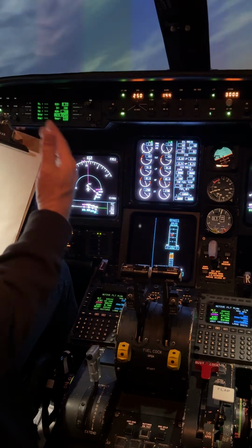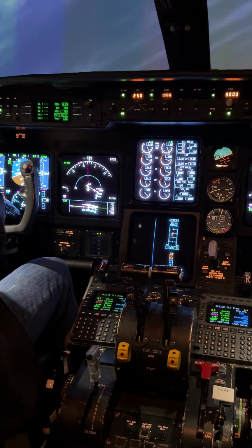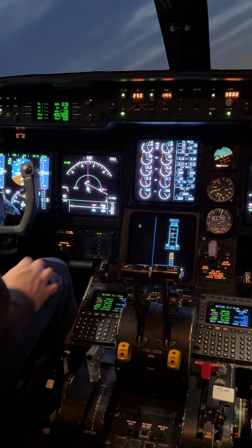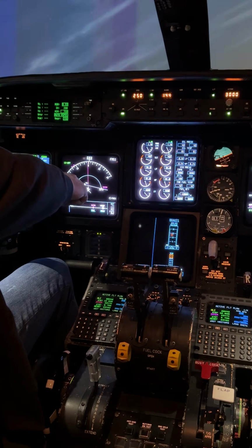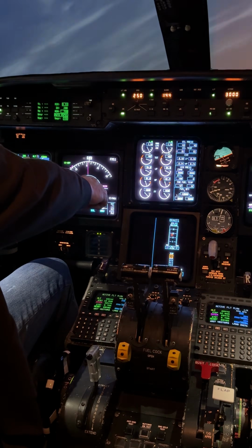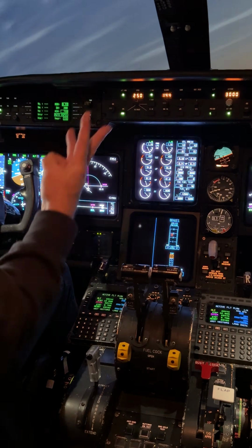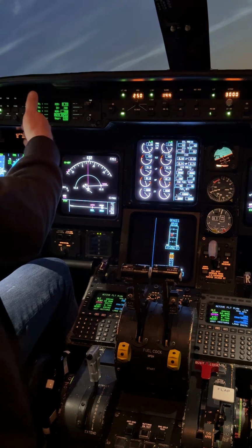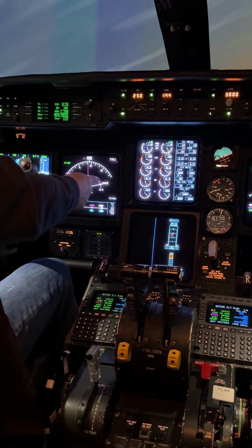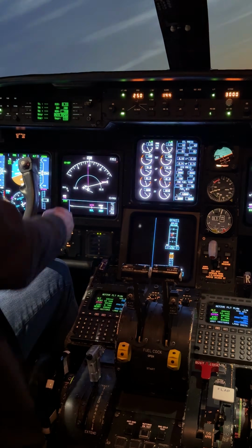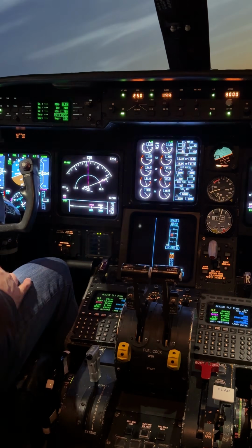So we're going to assume that we're cleared. The airplane is now doing a smart turn. I'll bring the range in just a little bit. Doing a smart turn from HLI to item. Are we established now? No, we are not. We need to be on an established part of the route for the approach. Right now, we are not established, so we have not met the three items we need to meet. We're cleared, our altitude is 3,000, but we are not established yet. Once we roll out and going direct to item, from HLI to item, which the airplane is attempting to do now, then we will be established.